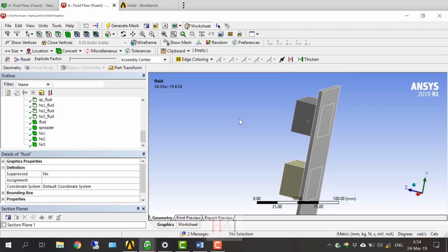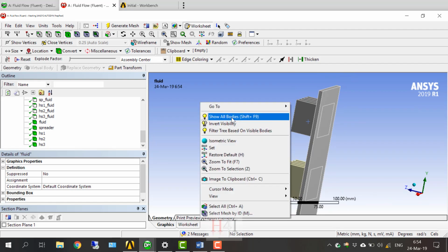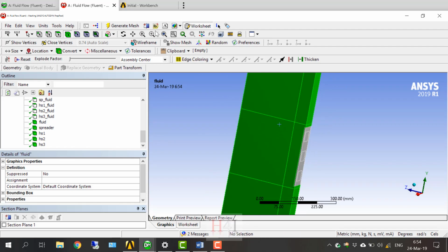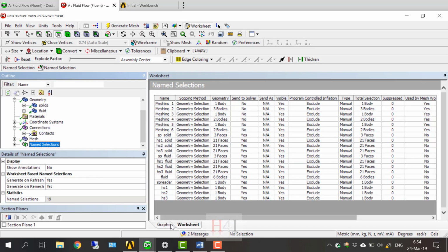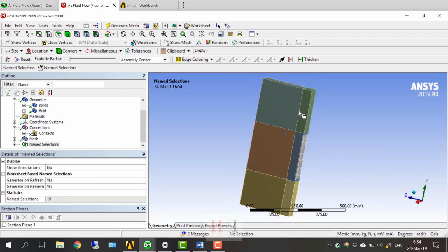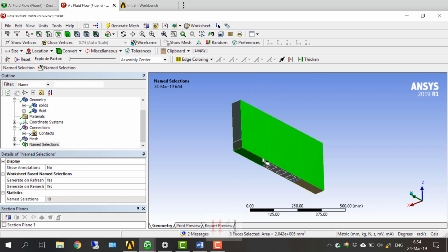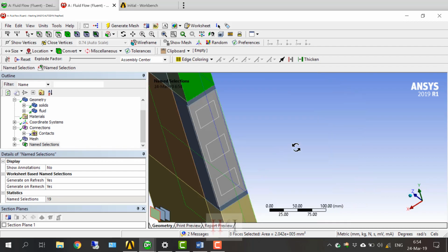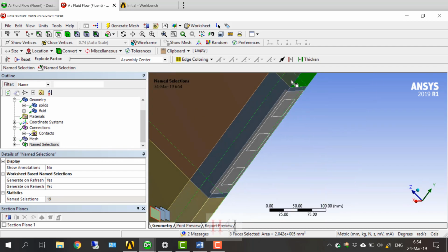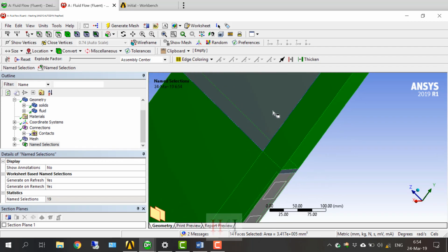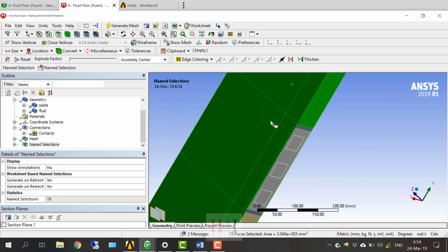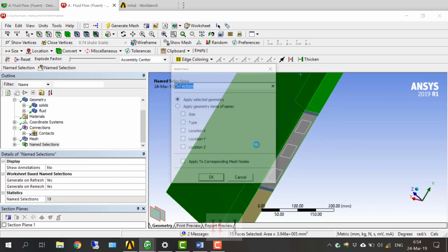Okay, we have time. I need to say something about this. What is the boundary you think I will define? I need to think the symmetry boundary condition, of course, these sides, as I said before, these are symmetry. This side symmetry, and this is symmetry wall. So let's define them. Those are easy ones. And I think the far one is the pressure outlet. Okay. Pressure outlet. Is there outlet flow from them?